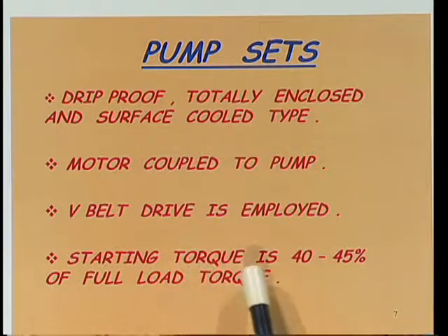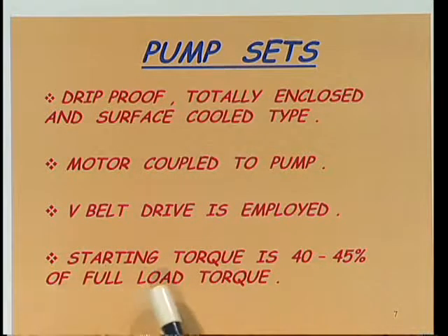Starting torque is 40 to 45% of full load torque. So for pump sets we require starting torque. Approximately, the percentage will be 40 to 45% of the full load torque if you calculate.